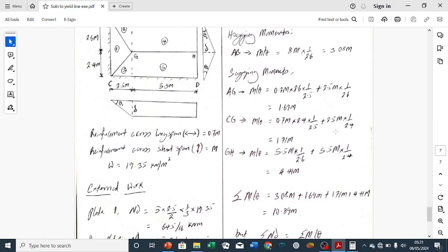We now go ahead to calculate the horizontal component, which is this one. The horizontal component will be resisted by vertical reinforcement, and vertical reinforcement has value M. So we have M here, while the length is 2.5, and the distance from this place to the point of rotation is 2.4. That is why our theta is 1 over 2.4, and so we do that, we have 1.71.